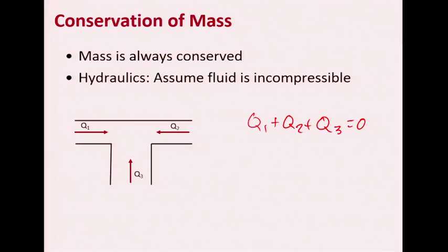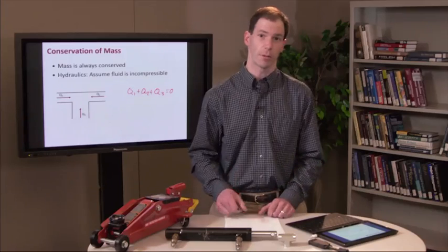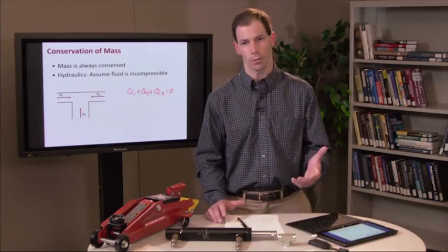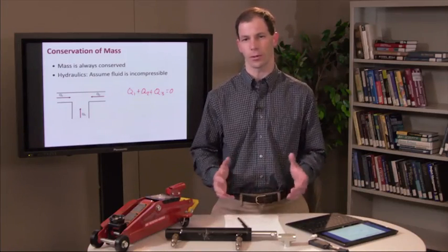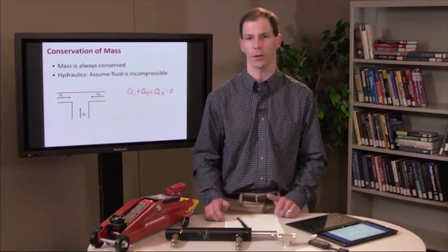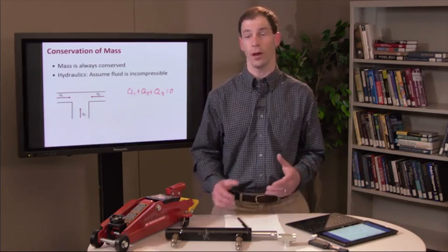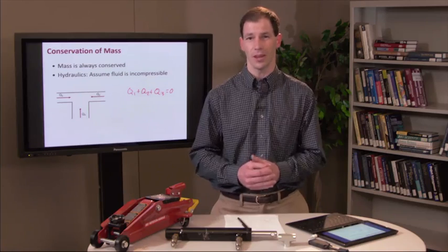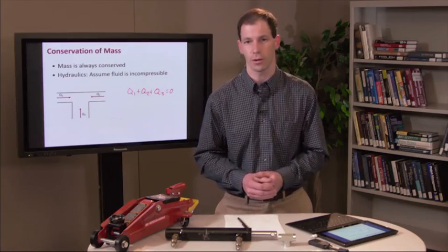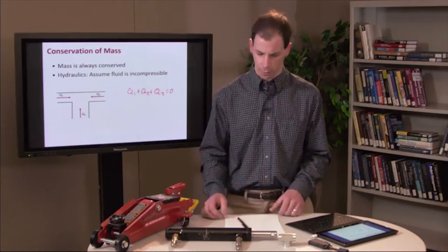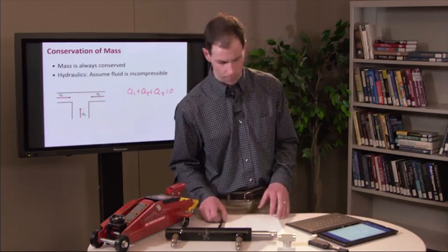So the natural question here is, is this a good assumption or not? Is the incompressible assumption good? Typically hydraulic oils, and water as well, are somewhere 2 to 3% compressible at the pressures we're dealing with. So these are relatively good assumptions for the majority of the time, although the compressibility of the fluid, which was referred to through the bulk modulus, does become important during some situations, and we'll talk about those later in the class. But for now, the incompressible assumption is a relatively good one.